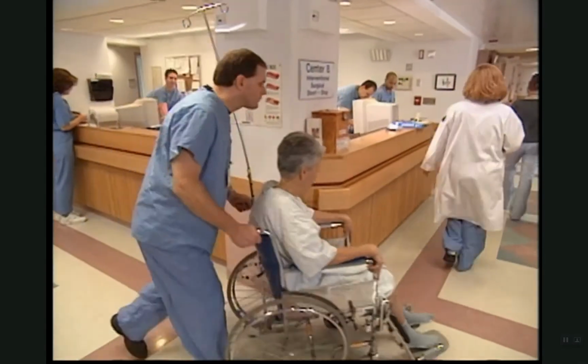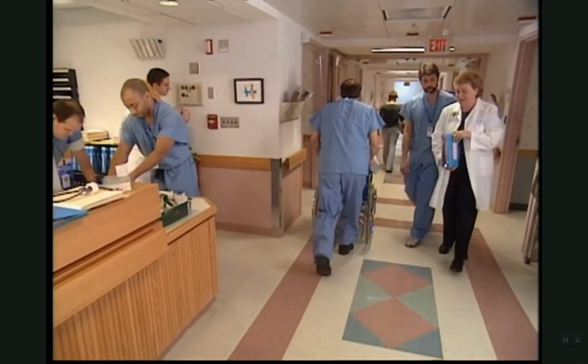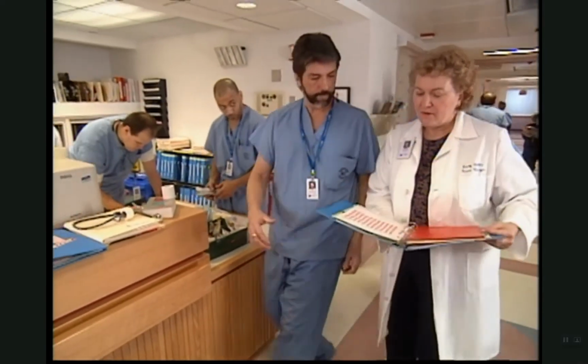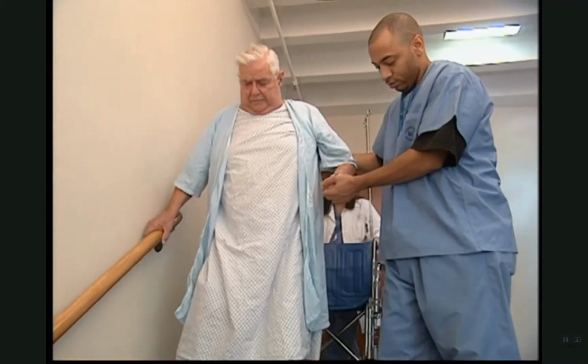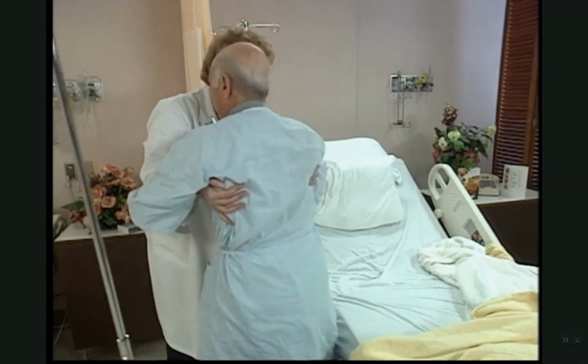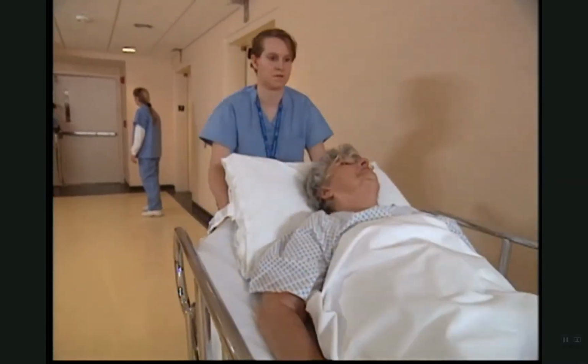Private mode notification appliances may be necessary in settings such as hospitals, where not everyone can or should get out of the building right away. When privately notified of the alarm, staff can initiate emergency response procedures that are appropriate for the situation.